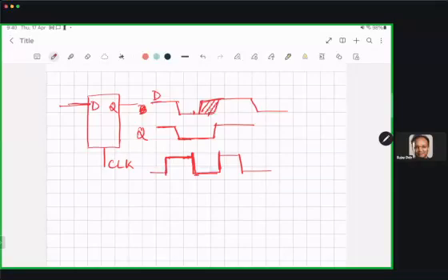I'll just make some connections. I gave you a chip which has a 2 to 1 mux, and I am giving you some wires and telling you, okay, make some wiring and apply your input and clock, etc. in appropriate pins so that this 2 to 1 mux becomes a latch.